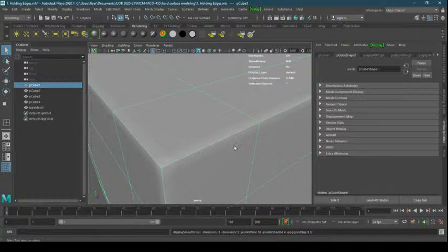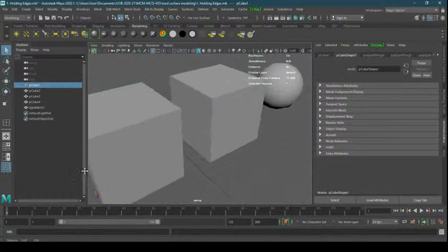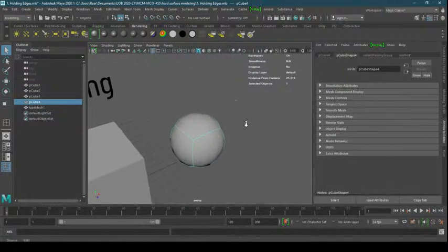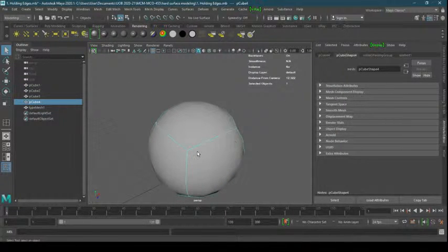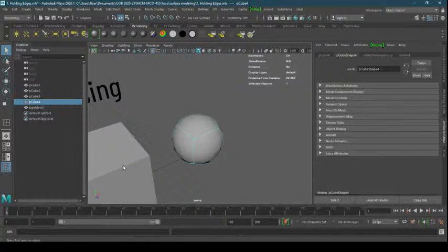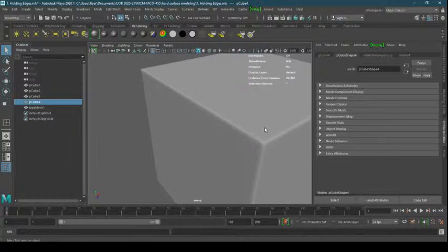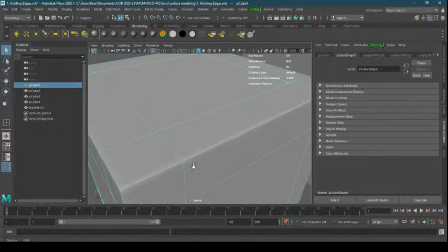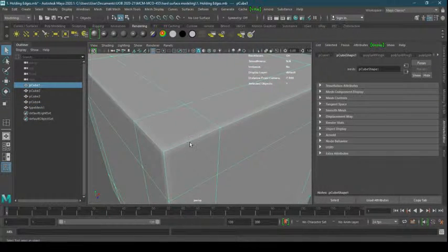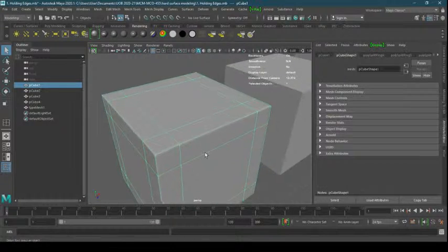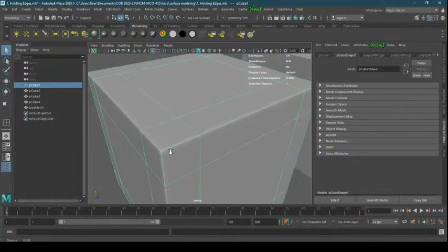If there is no holding edge, it will look like this, because there is no holding edge on the top or on the bottom of each edge. So what is happening is they are getting softer. So holding edges hold the existing edge in its position and never let it go out. So this was done with the help of, you can say, inserting an edge loop.